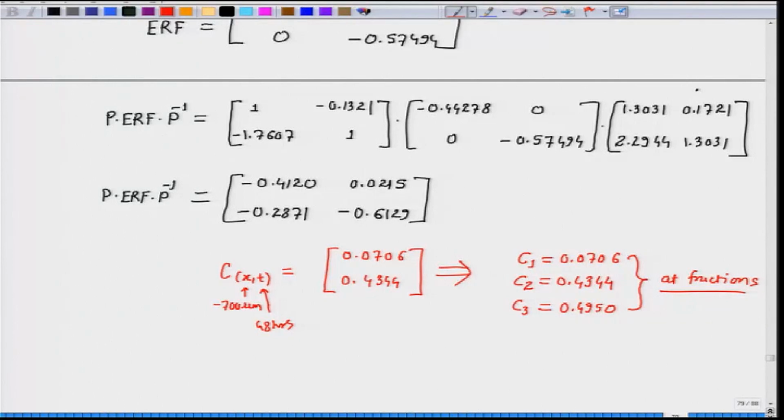x and t in any multi-component diffusion couple. Again, we illustrated this with a ternary diffusion couple, but a similar procedure you can apply to quaternary, quinary or higher order diffusion couples. We assumed the interdiffusivity matrix is constant throughout the diffusion zone, and also molar volume was assumed constant. So instead of moles per centimeter cube, we can also use the atom fraction or even weight fraction, because molar volume is constant, it is independent of composition.